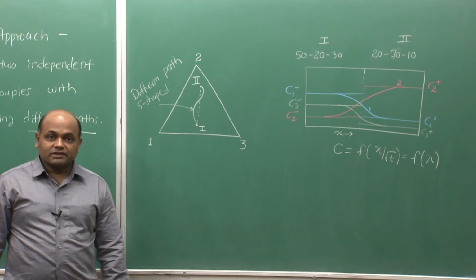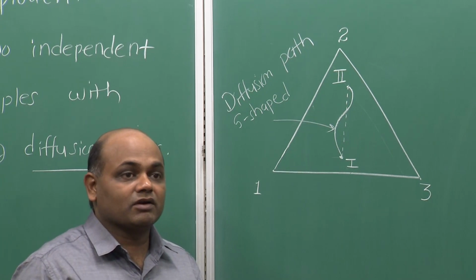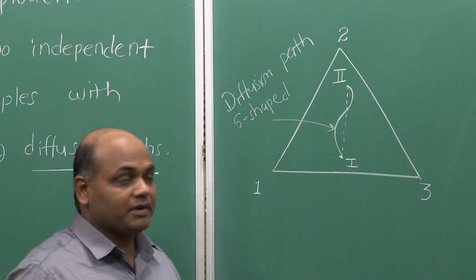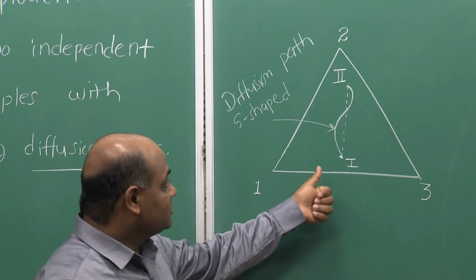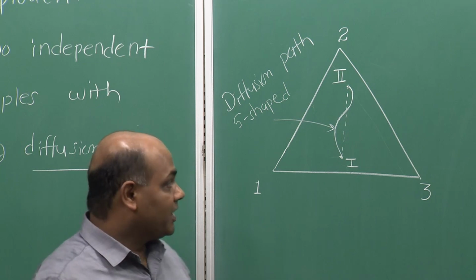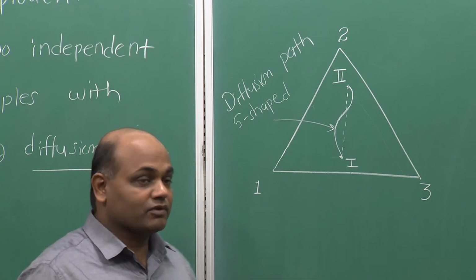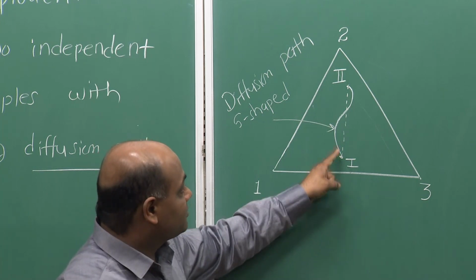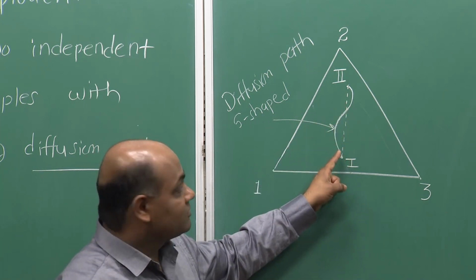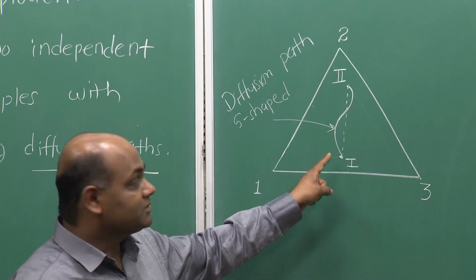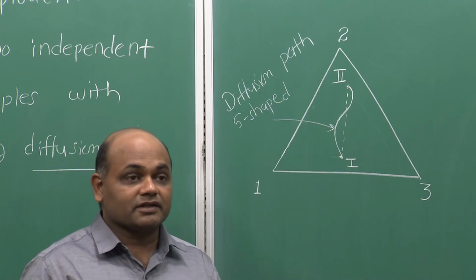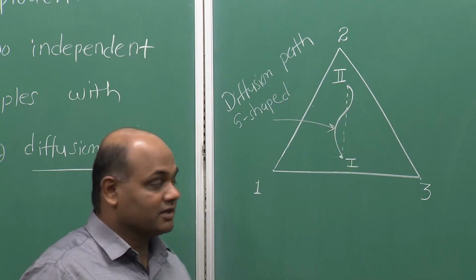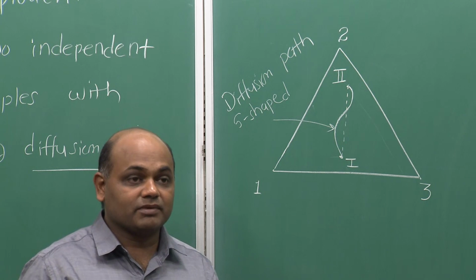When we conduct diffusion couple experiments, in order to assess the reliability of our experiment, we should usually prepare at least one diffusion couple at 3-4 different times, the same couple, that is, the couple between the same two terminal alloys annealed for 3-4 different times. I have to make sure that at different times the diffusion paths are the same. So, that helps to establish the reliability of the experiments.